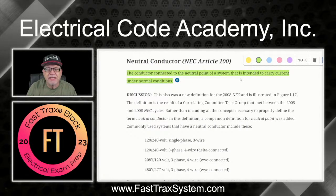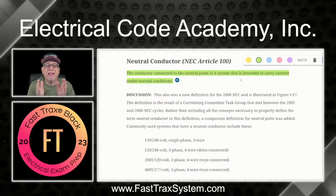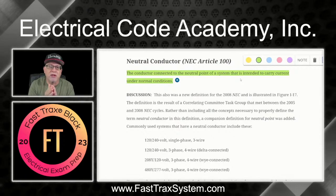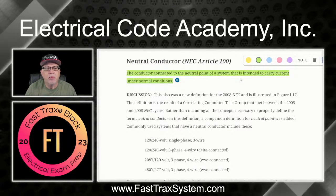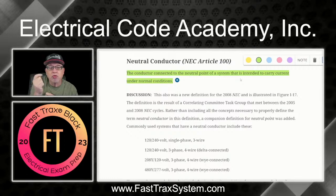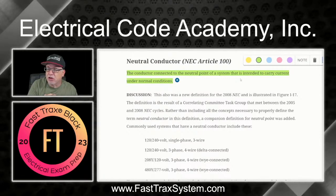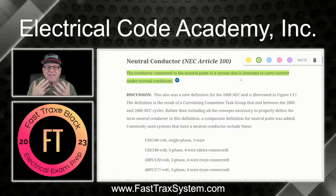Very different from an equipment grounding conductor, which in the service does connect to the same bus as the neutral conductors. But as it leaves your service and goes out, it's important to realize that the equipment grounding conductor is to carry fault current. It's not expected to carry current under normal condition, only under an abnormal condition, whereas a neutral is going to potentially carry current at any given time. So it's an important distinction.